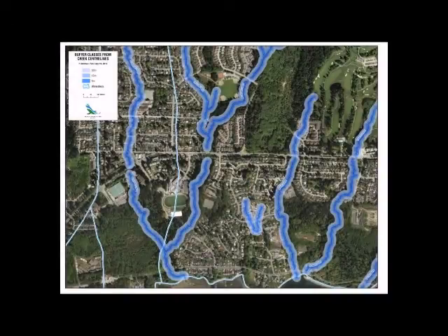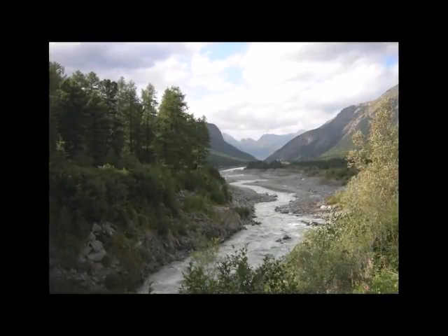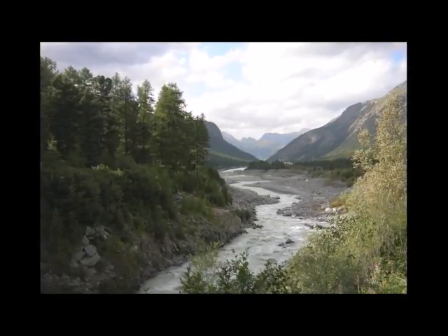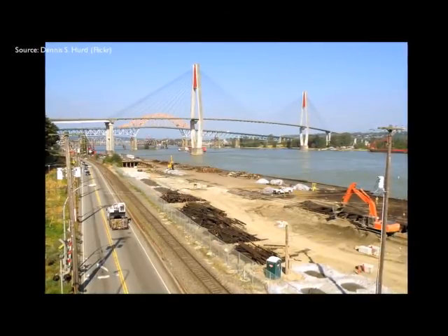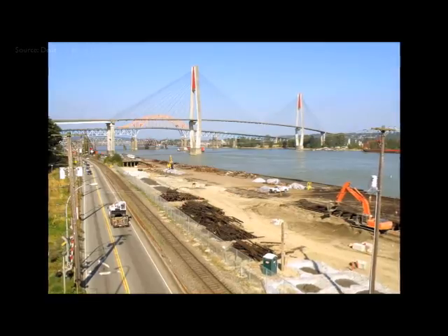Current riparian areas regulations in the lower mainland of BC require a 30-meter wide vegetated buffer zone on both sides of a stream corridor, containing only developments that will not result in harmful alteration of fish habitat. However, research has shown that aquatic ecosystem protection is enhanced with a 60 to 100 meter buffer strip. Competing land uses on a limited land area make these wider buffer zones difficult to implement in an urban environment.